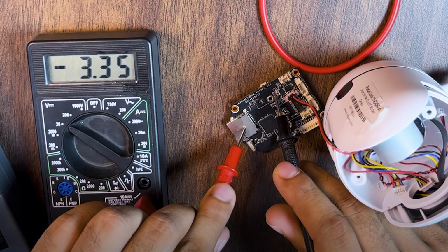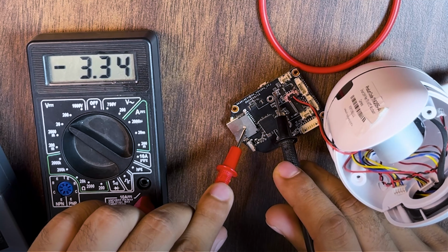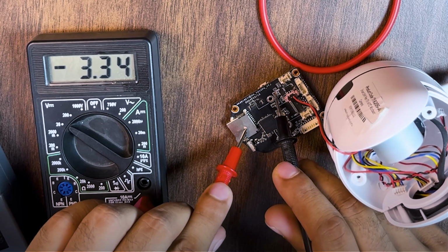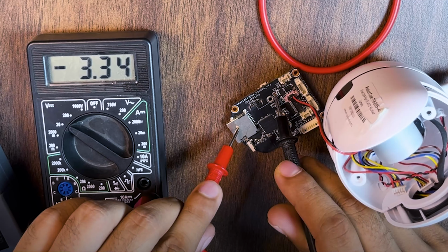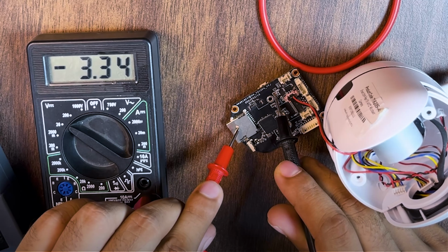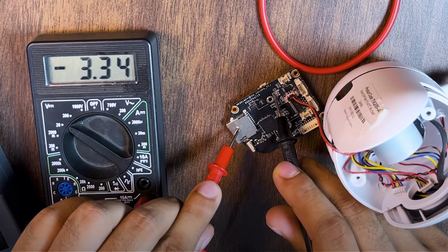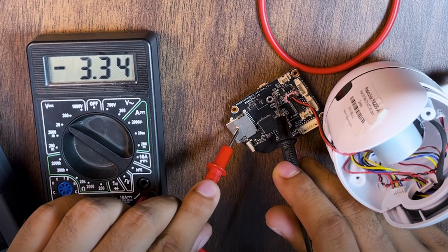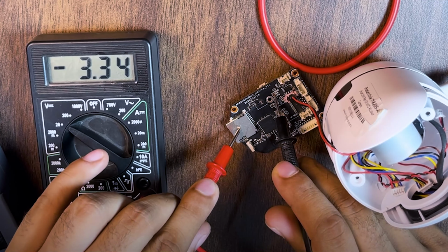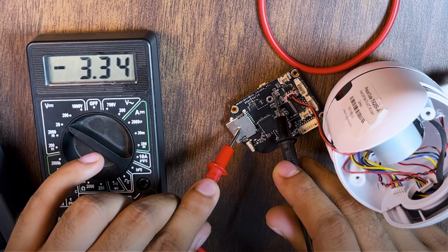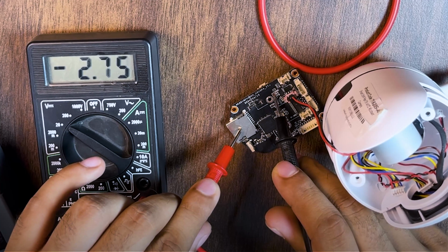And now what you're seeing is a stable voltage at around 3.35. The small fluctuations that are coming could also be because I'm speaking, so my hands are shaking a bit, and there could be certain disconnection like I did right now. However, we can consider that the average voltage is going to be around 3.35. And usually when you're measuring the RX port, during boot up or after boot up, you are idling at high. So 3.3 or 3.34 volts is what it is idling at. So we can consider that this is indeed the RX port.